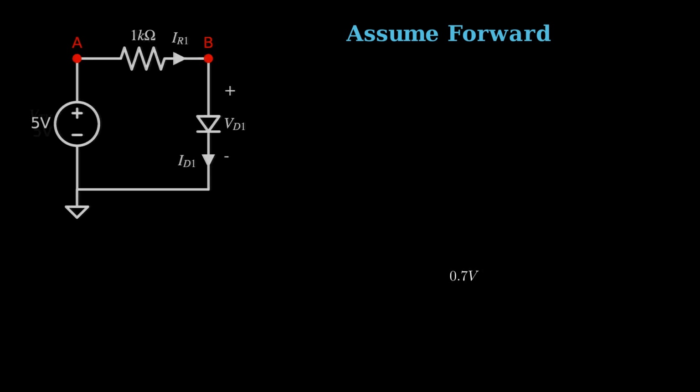Let's use the 0.7 volt assumption in a linear system developed using nodal analysis. With only two unknown node voltages, I only need two equations to find them. As I usually do with nodal, I start with finding voltage sources and writing a KVL for each. I'll do that for the 5 volt supply. And in this case, since we've assumed a voltage across the diode, we treat it the same as the voltage supply, with the positive side of the voltage on node B and the negative side of the voltage on ground, we get this KVL. For this circuit, that is it.